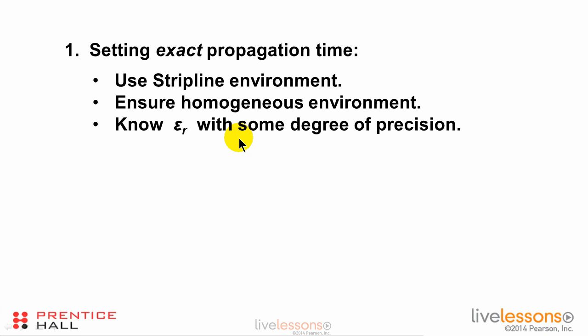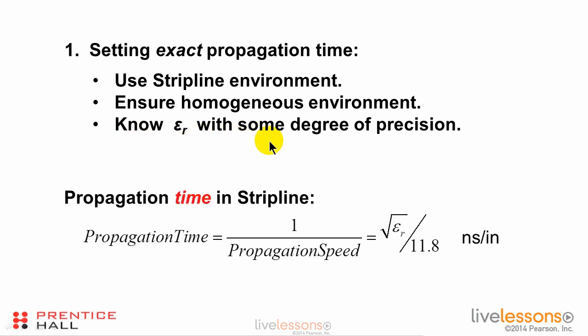I said, okay, now if I specify a relative dielectric coefficient of 3.7, where is that? And he pointed to the same material on the same shelf. I was somewhat dismayed that they weren't going to pay any attention to what I specified, and that is a problem for us as designers to actually know specifically what the relative dielectric coefficient is.